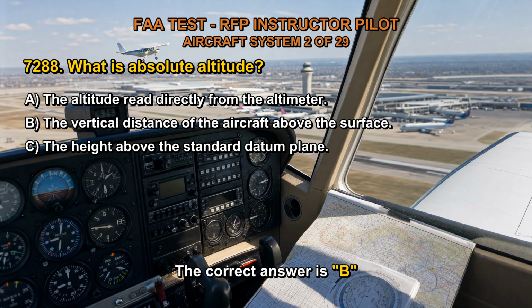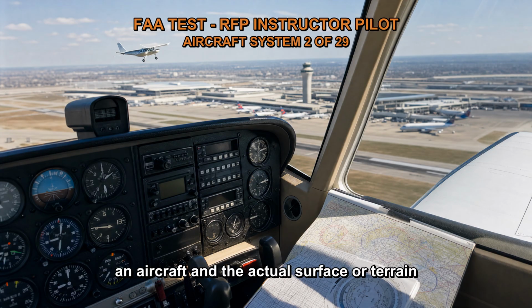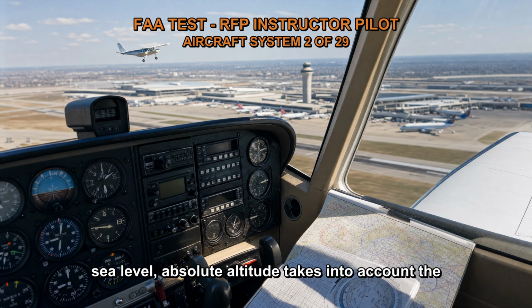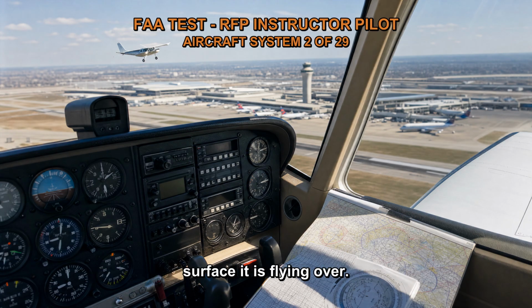The correct answer is B. Absolute altitude refers to the vertical distance between an aircraft and the actual surface or terrain below it. It provides a measure of the aircraft's height above the ground, rather than a reference point such as sea level. Unlike true altitude, which is measured above mean sea level, absolute altitude takes into account the variation in terrain elevation and provides a more practical measure of an aircraft's height above the surface it is flying over.